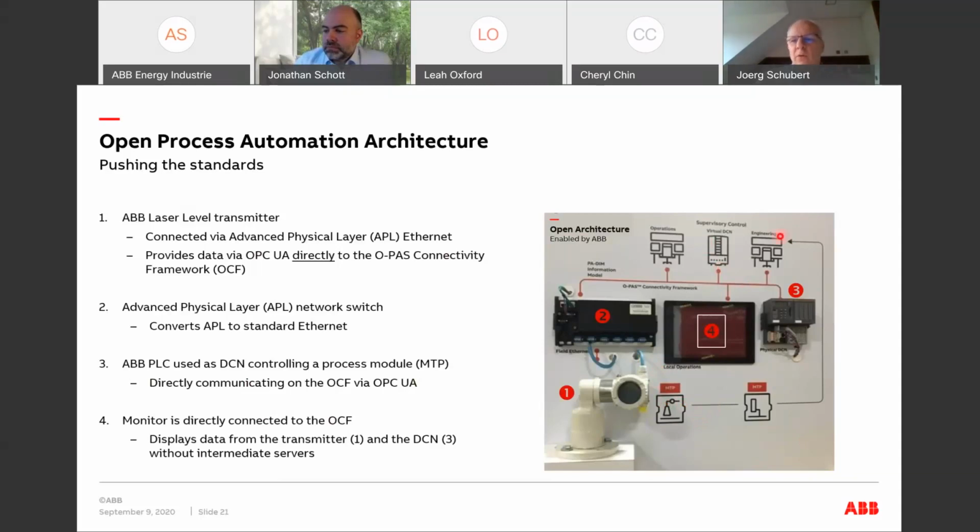So you could in this picture probably say on the upper right side, including this PLC, that is more or less the same scope that you have seen before with the other demonstrator. It was an OPAF or open process automation system with an advanced computing platform with virtual DCNs on it, an HMI and engineering, and the DCN down here. What we are adding in this is that we are making use of the Ethernet technology going all the way through to the connected field instrument.